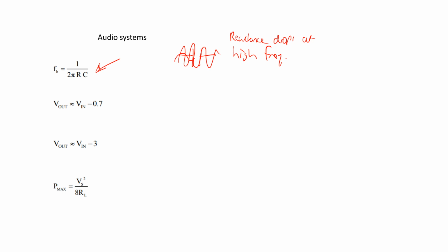These equations are just basically to show you that if you've got an emitter follower power amp, you have to take 0.7 off. Bog standard emitter follower, you'd have your speaker, something like that. Really badly drawn speaker. There's my speaker. So the idea is V out is 0.7 volts less than V in. Do the same with the MOSFET, but obviously take 3 volts off for the MOSFET.